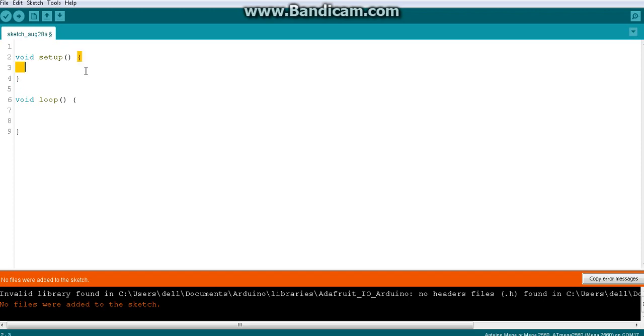And when we are trying to give an analog output, the voltage we are supposed to divide is broken into 256 units. That is why we have 0 to 255 values. So when it is analog input, the maximum value will be 1023, and I'm sorry guys, when it comes to analog output, the maximum value will be 255, right? I explained that. If that was a little bit messy to you, don't worry, while we are doing some code and practicals, you will understand this.